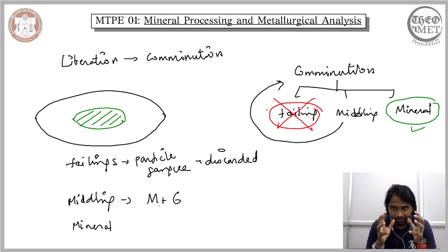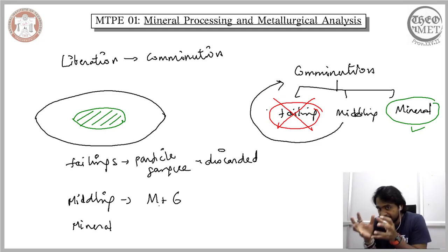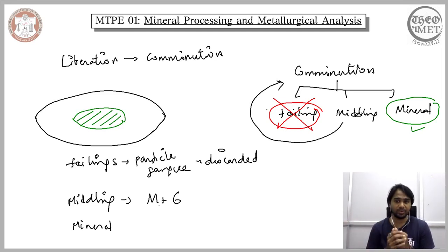One critical factor here is, even though it is possible for us to arrive at a uniform size of the final particles and thereby increase the degree of liberation, we never do that. We subject only the middlings to the second level of comminution. By doing so, of course, at the end we will have a non-uniform size distribution in the end fragments, but this will save our expenses. So instead of reducing the particles from the initial stage alone, we plan it in such a way that we undertake two or three stage comminution. We just subject the middlings to the subsequent comminution, and do not impose a comminution that directly renders small particles. This is done exclusively for the sake of our economic benefit.